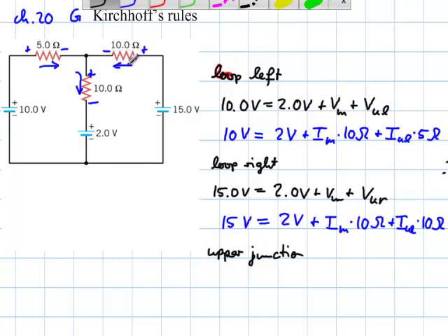What would happen then is that the current that we come up with would have a negative attached to it, and that would tell me I have to turn it around and come up with the right one. If, in this case, all our currents come out to positive numbers, then I actually have chosen all of three of them correctly. But we can see that later.